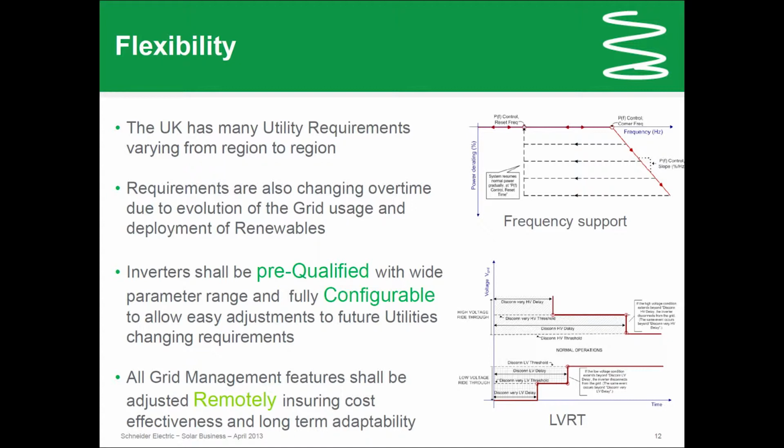So you have to have a very large window of different voltage inputs, a very large window of frequency change, also being able to manage the cos phi or the reactive current, and also manage power that the grid might try to inject into your inverter. So how are you going to react to that? And you need to protect yourself.